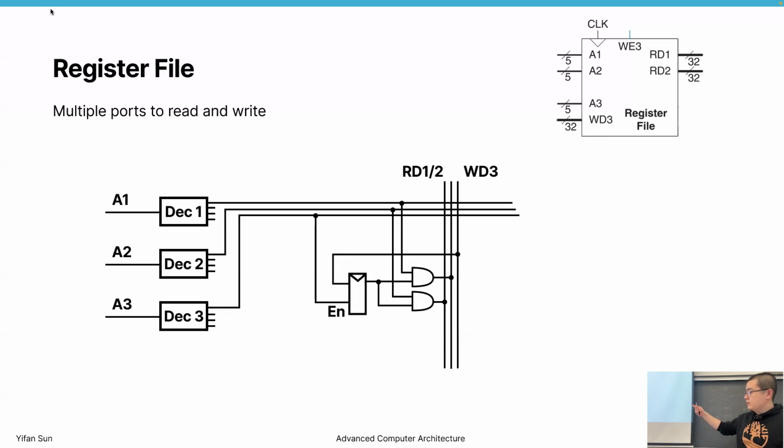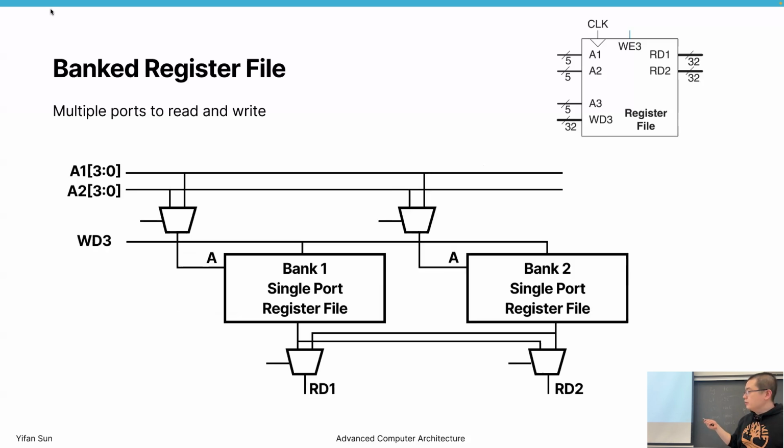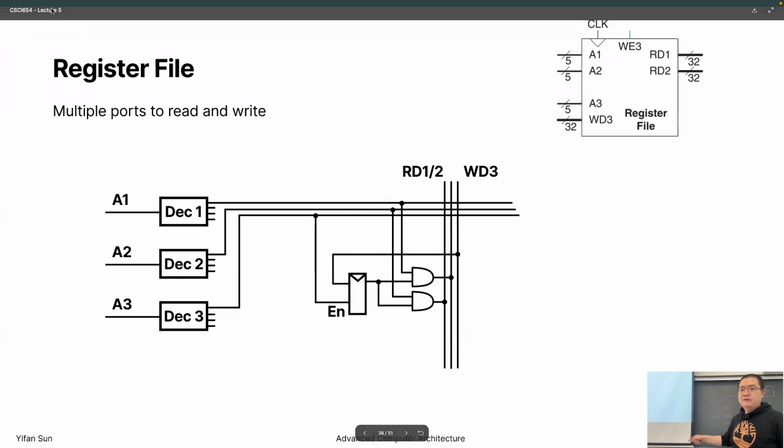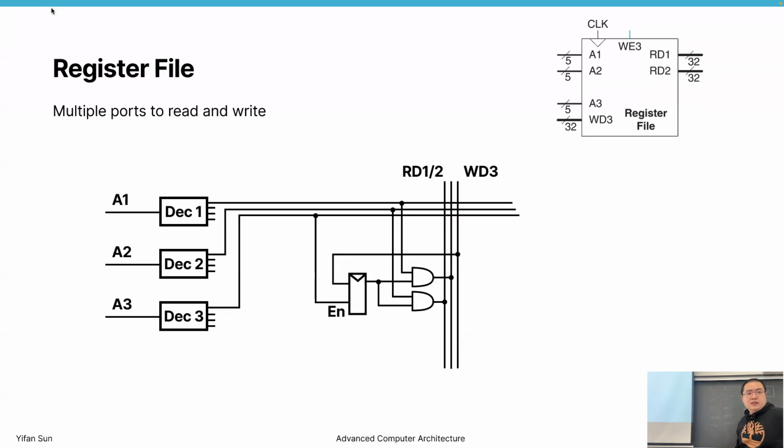So we're just using this as an intermediate step to go to our final step. That in actual GPUs, how the register file is implemented in a banked style. So they cannot really have so many wires that go through every cell. Right? It's a lot of wires. So instead, they find some trade-off.